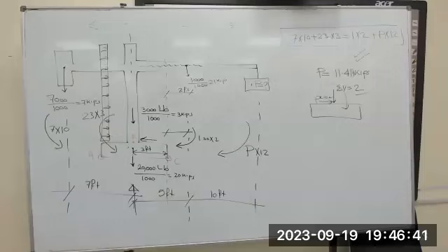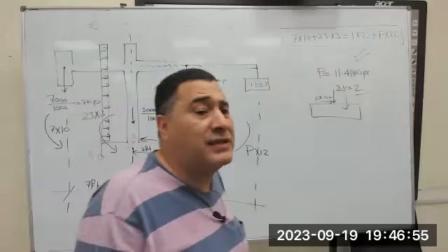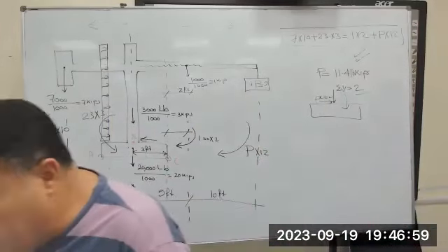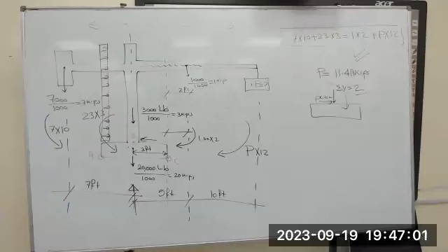When we have this, they are telling you to validate the design. Validate the design means what? Get the action load from a third party, especially if you have a pre-engineered section. Kirby, for example, they have their own standard. They have their own section.